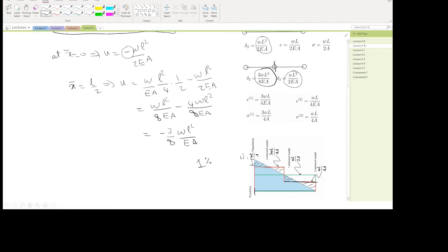And you can think about this in different ways, and you can split it into smaller and smaller parts. So each part would be related to the size of the error you're missing. And if you think about it in this way, you will be able to find some sort of a relation, so you can estimate exactly what would be the error for a certain number of elements. Okay, so the number is 50 elements. Now think about it, 50 elements. So you need to have 51 equations to solve in order to be able to get 1% error.